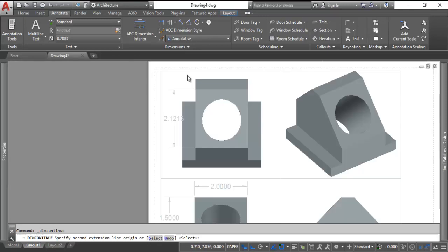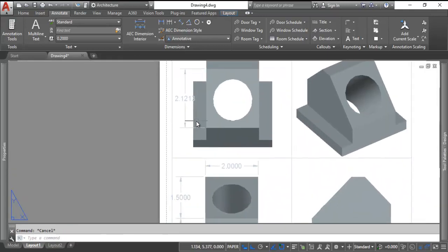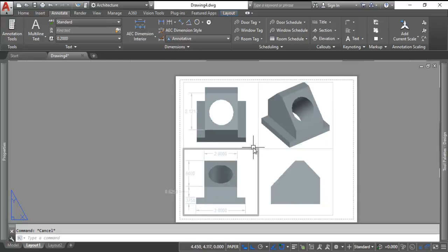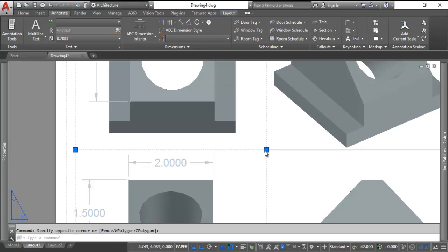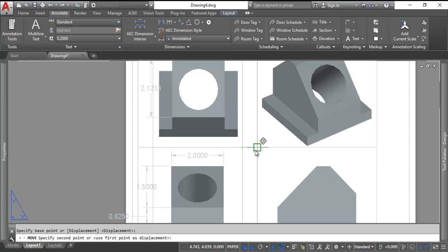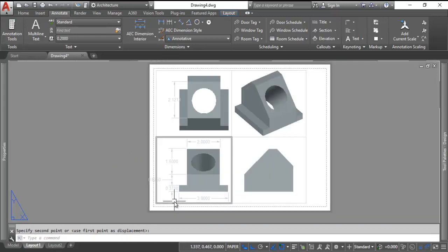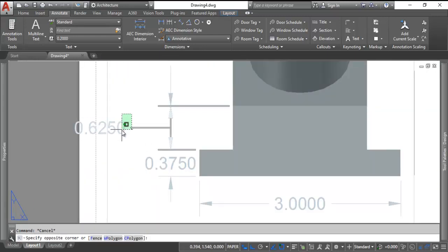And we can continue dimension. I don't think we will. We'll leave it just like that. That's the only dimension. Now when you are doing dimensions, you can see that some of these are going off the page. So what I can do is stretch just those two viewports over, and then use the move command to move them to the right, and that buys us some space, and then I can stretch these viewports completely over. And these dimensions are alive and active, so if I pick that text, I can grab a grip point and force it closer wherever it makes sense,